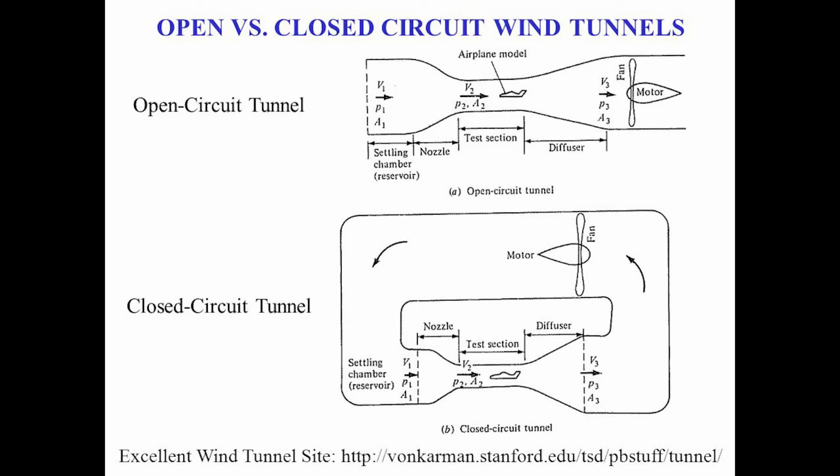But generally speaking, you can think of the anatomy of a wind tunnel as being 3 or 4 sections. In the case of the open wind tunnel, you have a motor-powered fan sitting towards the end of the diffuser that pushes the air through the tunnel. The diffuser is there to slow down the air and minimize energy losses, and you'll probably understand this better after Larry's lectures on one-dimensional isentropic flows. Okay, so that was the diffuser, but at the front of the intake, you have a converging section here.